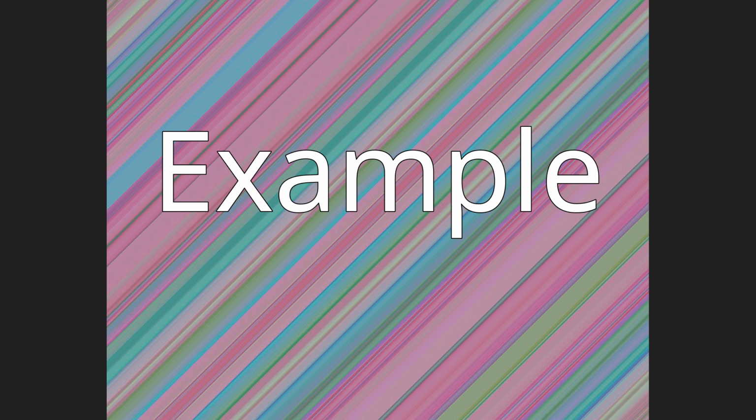The COP of a heat pump or refrigerator operating at the Carnot efficiency has in its denominator the expression TH minus TC. As the surroundings cool, TC reducing, the denominator increases and COP reduces. Therefore, the colder the surroundings, the lower the COP of any heat pump or refrigerator. If the surroundings cool, say to 0 deg F (minus 18 deg C), COP falls in value below 3.5. Then, the same system costs as much to operate as an efficient gas heater. The yearly savings will depend on the actual cost of electricity and natural gas, which can both vary widely.